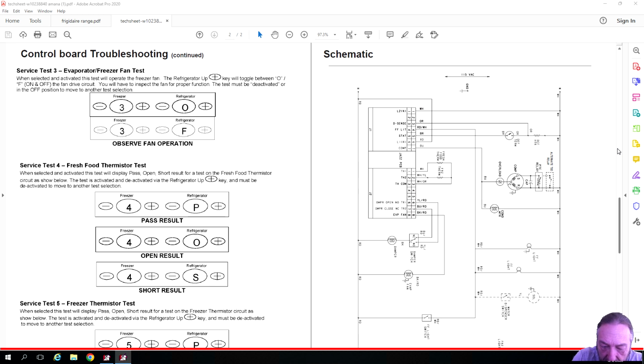The red and white is going to pin 4, and the red is going to pin, well, where is red? Red is going to pin 6, like the diagram. If you look right here, red is pin 6, pin 4 is red and white, and then white over here.